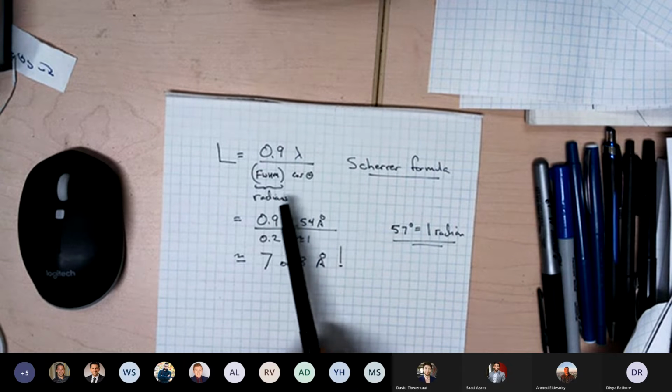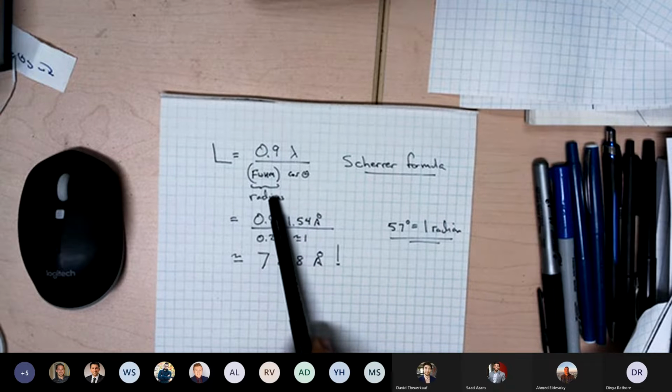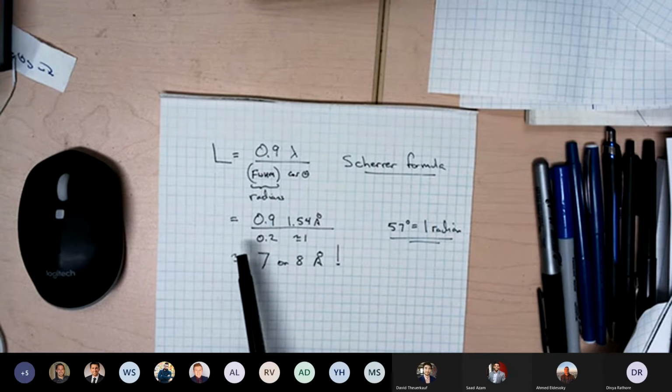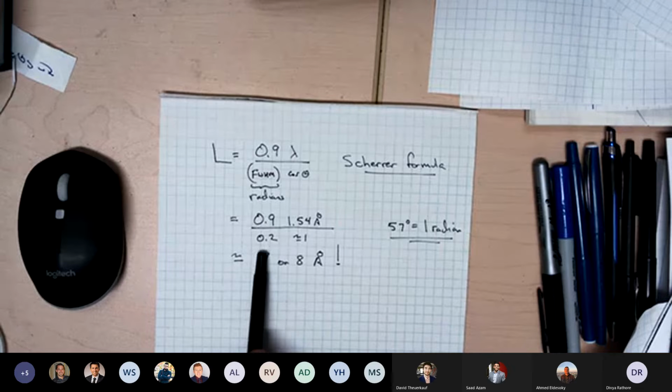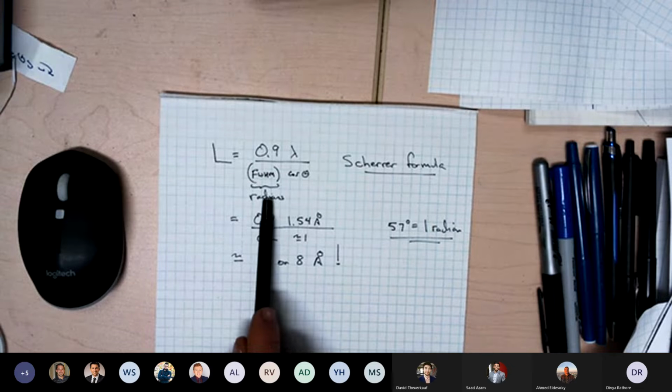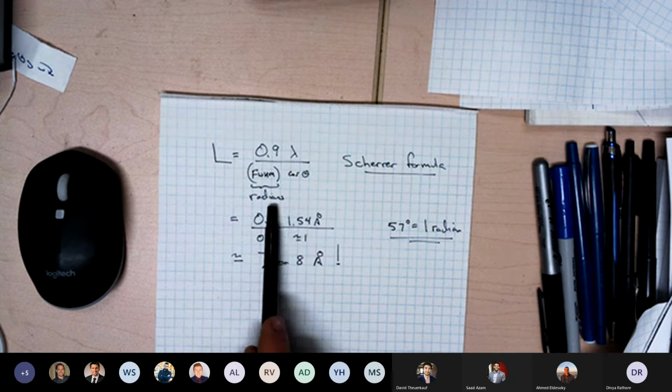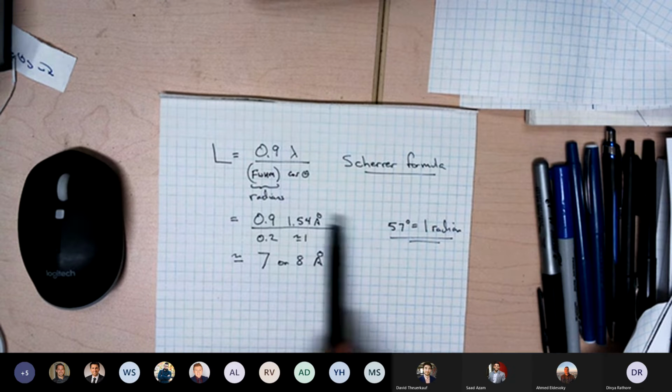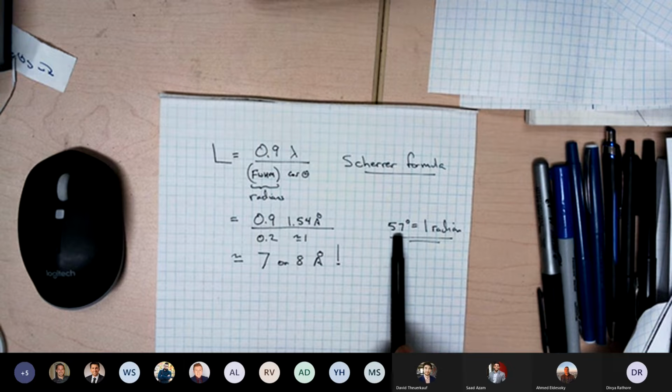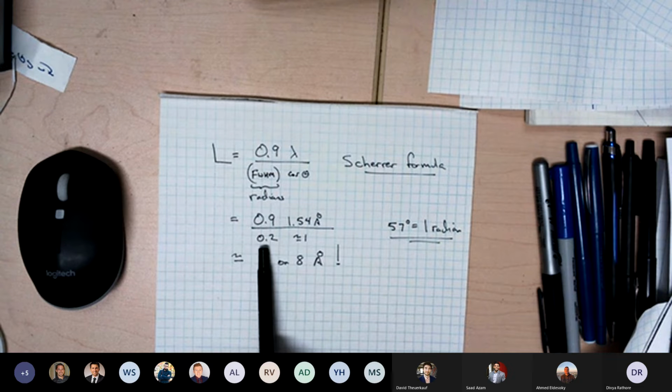Anyway, it doesn't matter the details. What does matter is what happens if you work this out for the X-ray patterns I showed you on the previous PowerPoint slide. So for the hard carbon precursors, which were in the right graph, the full width half maximum of the peak was about 10 degrees. And because 57 degrees is 1 radian, 10 degrees is about 0.2 of a radian.